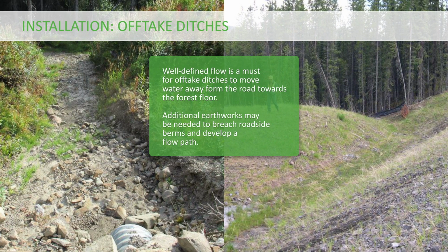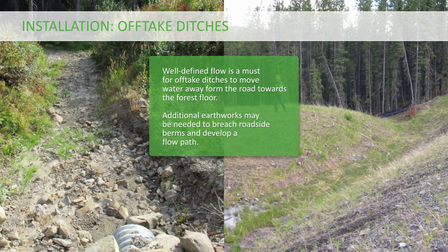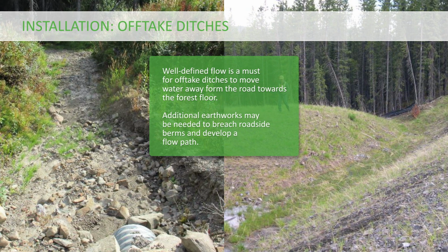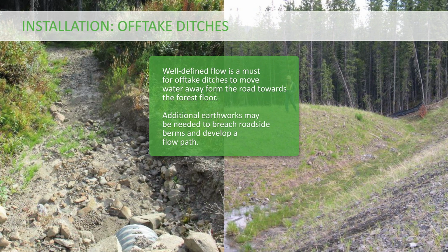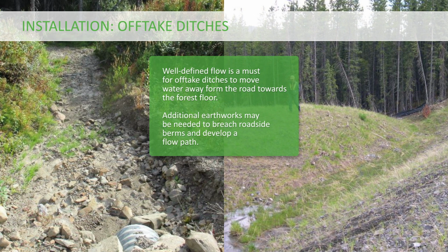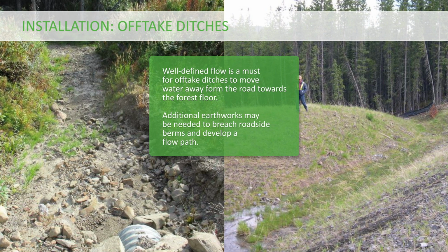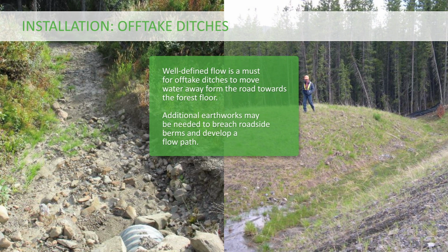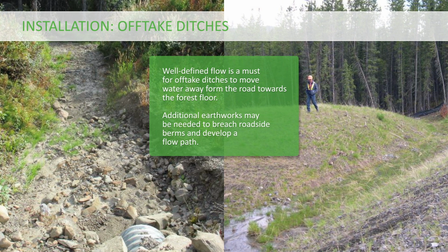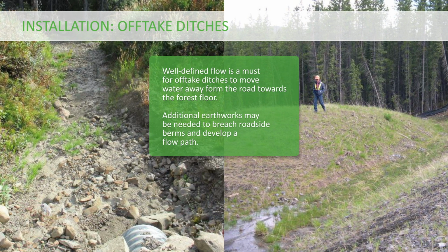Site-specific alterations may be required, such as additional earthworks to breach roadside berms and ensure a well-defined flow path. This may seem like a lot of work, but operators have shared that breaching roadside berms is easily accomplished when using the appropriate-sized excavator. If there is any level of complexity at the site, use plenty of ribbon or construction stakes to ensure the plan is communicated adequately to those doing the work.